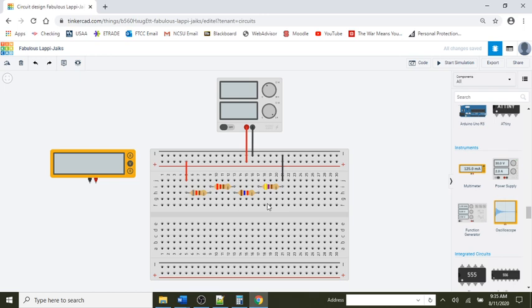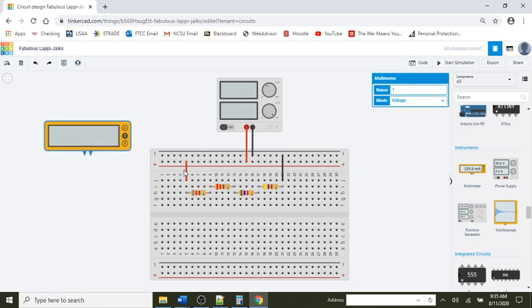But for current, you've got to actually alter your circuit by opening the circuit. Now I could open it here, here, here, here, here. I can open it at any point. It's a series circuit, so it's going to have the same current. But probably the easiest is just to go ahead and open it right here at the start.